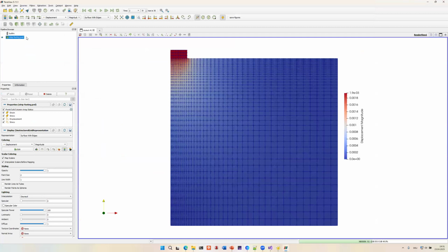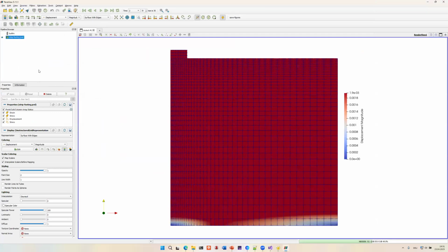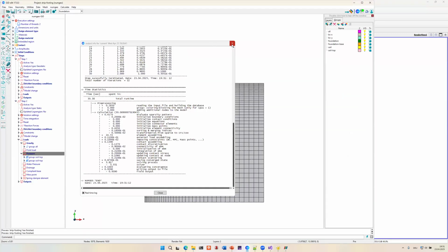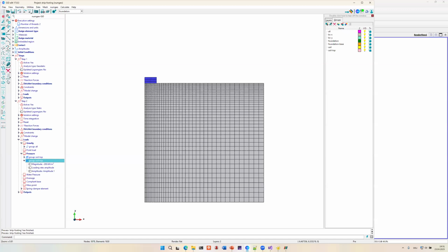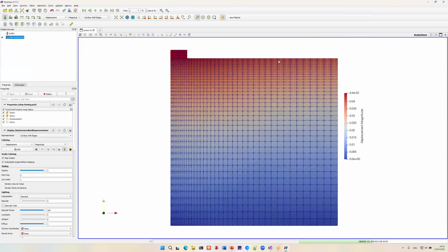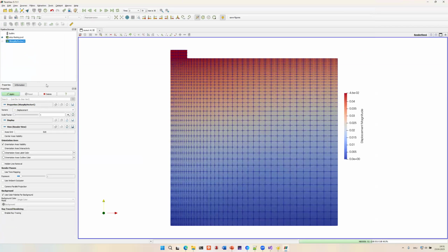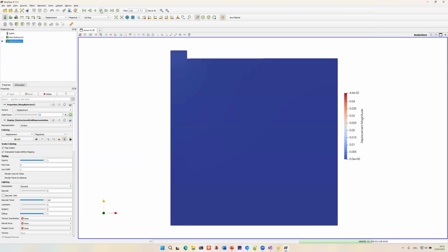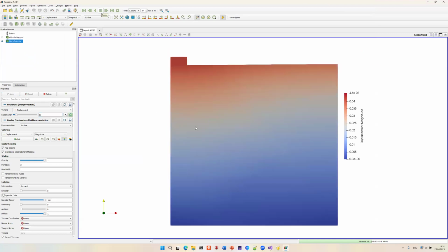Now what we can do is stay in that window. We just reload the files. And what we will see now is that we have in fact some loading. And now I think I did... okay, so now you got me. I did another error, and this is, I assigned it to the entire top surface. I mean, we can look at it, but that's why we have a big settlement for the entire foundation. So if you want to look at what is happening, you can see it. I applied the load now to the top surface, but this is obviously not what we wanted to do.